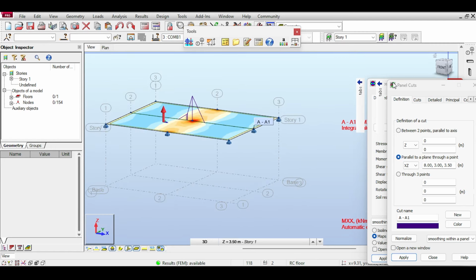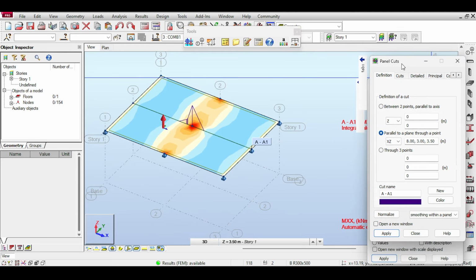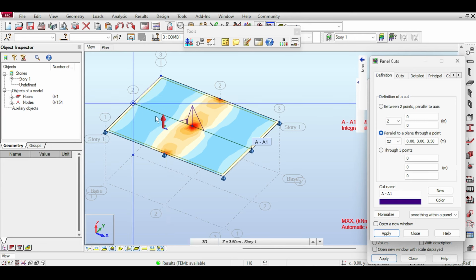So that is a panel cut in X, but this is a column strip and a central column strip. In order to design the plate, you would have to design it in the maximum section. Now, you can immediately see that the maximum section is happening here, so that's the section you should be checking out for designing. Now, you could do other sections.